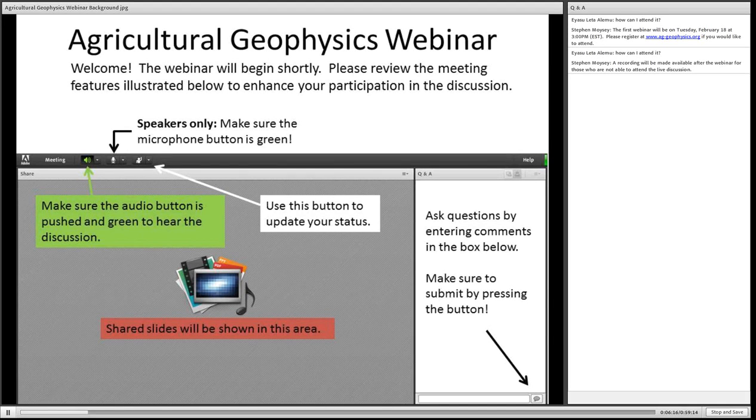Yeah, sure. Karst features are difficult to characterize with EMI unless they have some sort of conductive filling. Even if only a fraction contains conductive fluid, that fraction can provide a good response because it develops a pretty big surface area with conductivity that will really let current flow get going.